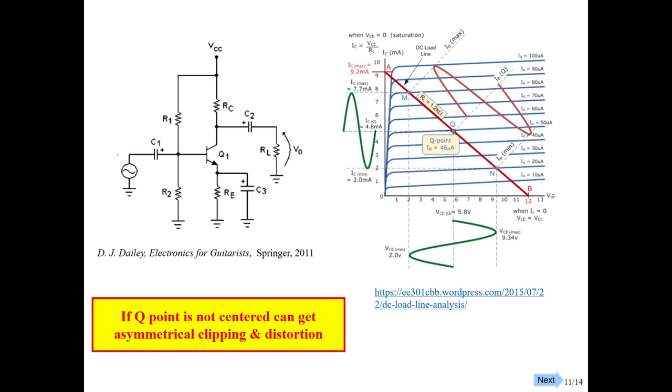Well, here is our VCE, so that's the voltage across collector to emitter, and here's IC, that's the current through the collector. And then as we vary IB, we move along these curves. So if you were to just fix VCE at, say, 6, and you were to fix, say, IB at 60 microamps, so you go up 6, 60 microamps, draw across that, you'd have 6 milliamps of current flowing in the collector.